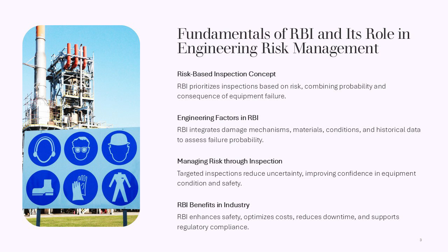Risk-based inspection, RBI, is a structured and systematic methodology used to prioritize inspection activities based on the level of risk associated with equipment failure. As defined in API Recommended Practice 580 and 581, 2023, risk is the combination of the probability of failure, POF, and the consequence of failure, COF.